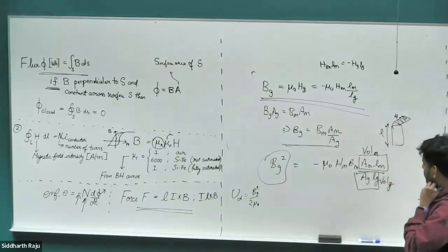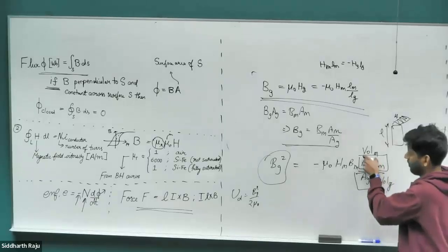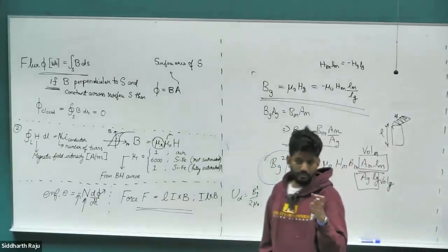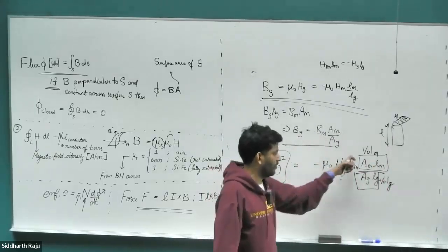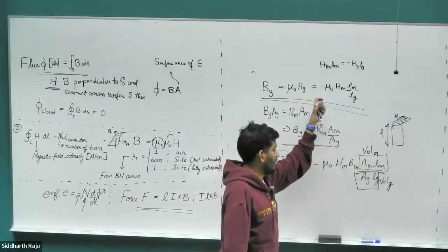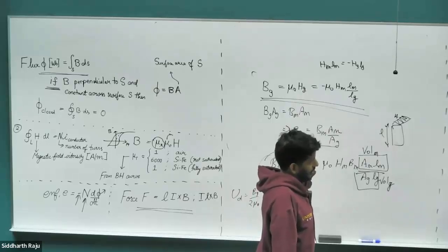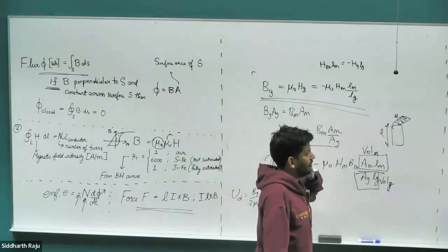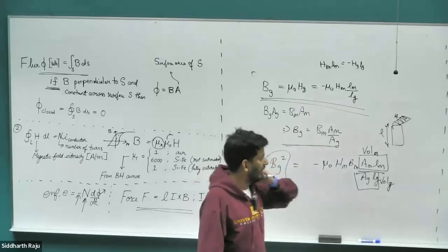Right? Our objective as designers would be to minimize the volume of the magnet, because the cost of the magnet is based on how much weight of the material you're using. And all of these are extremely rare earth. They're not rare in the sense of not being abundantly available. It's just rare in the sense of the people who are mining it are not giving it.